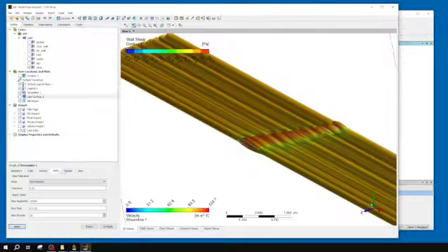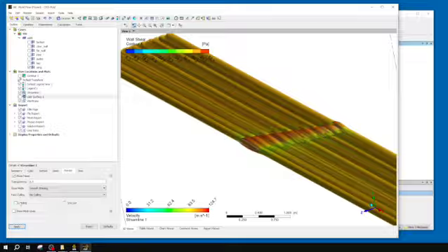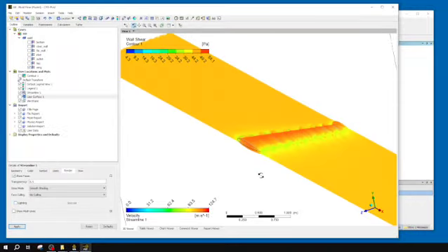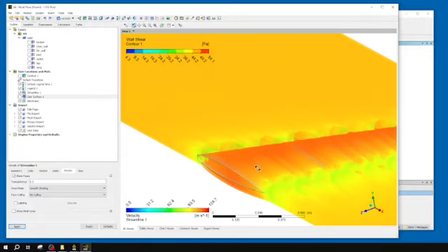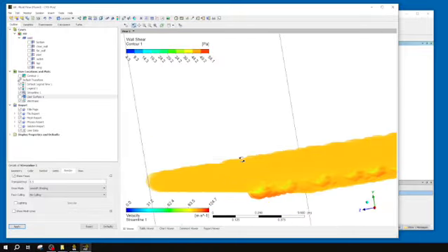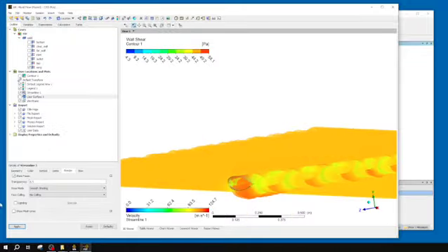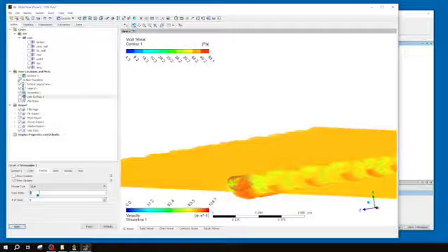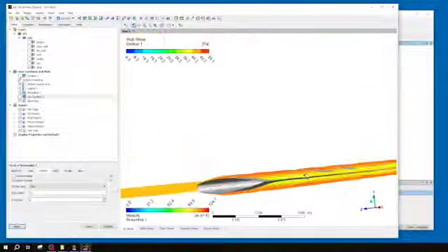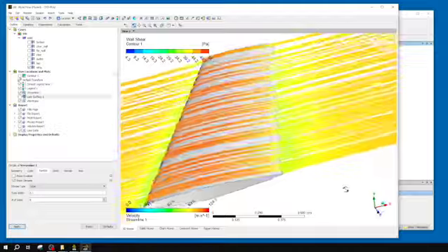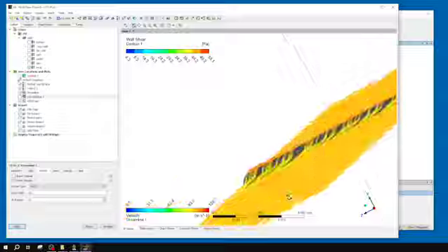Both tubes and ribbons don't usually work as well with lighting option enabled, so I usually turn that off, and that keeps them currently very bright, but we currently have quite large tubes, so I'm going to go back to my symbol. Instead of 1, I'm going to go down to 0.1. Let's see what those look like. Those look much better. So yeah, tubes are, as they imply, a tube.